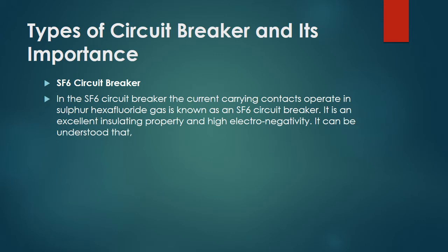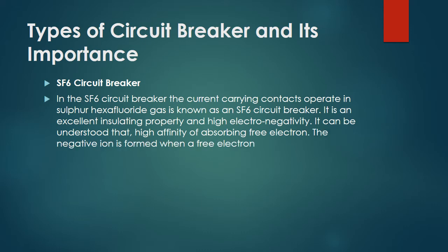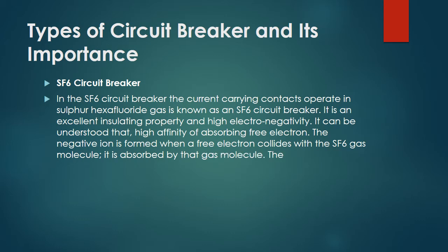Application and uses of air circuit breaker. It is used for protection of plants, electrical machines, transformers, capacitors, and generators. Air circuit breaker is also used in the electricity distribution system up to about 15 kV. Also used in low as well as high current and voltage applications.